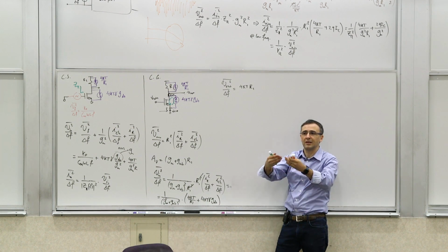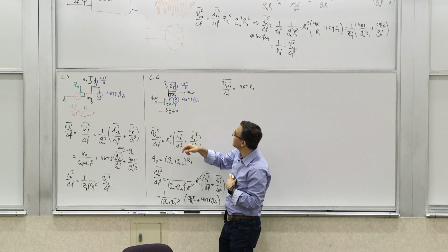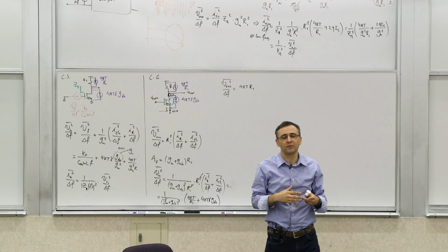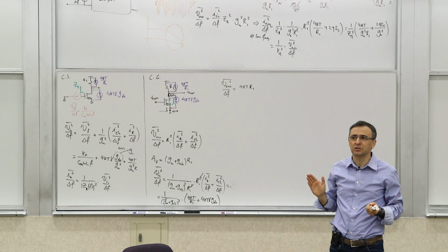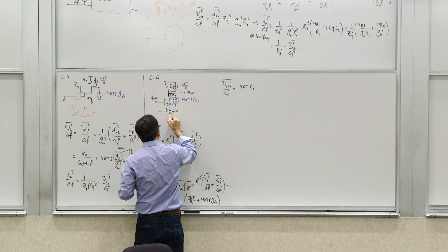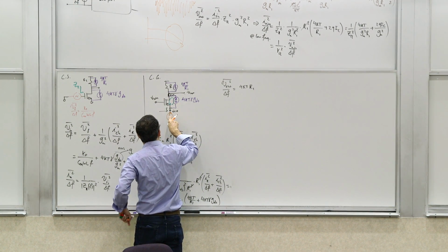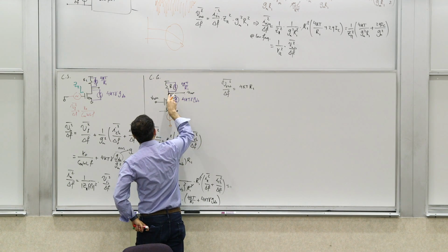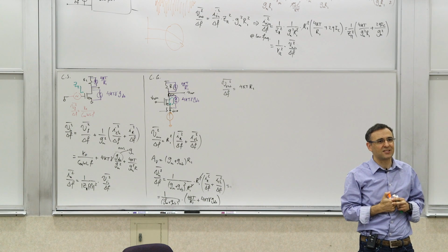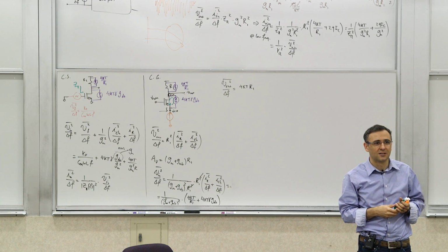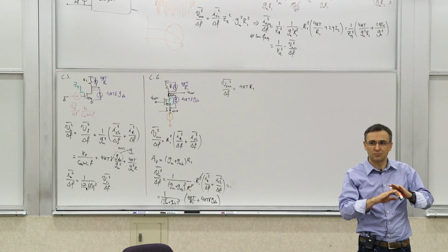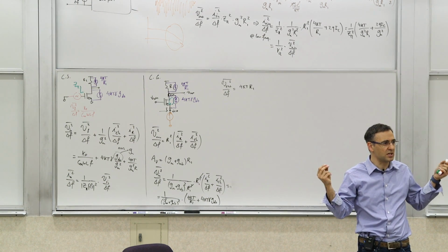And if you want to reflect it to the input, you have to look at the transfer function from that output voltage to the input current. What is it? Well, what is the transfer function from the input current to the output voltage for a current source now? If I put the current source back, what is the transfer function from this current to that output? What is the trans resistance, right? It's the ratio of output voltage to the input current. From a signal perspective, forget about noise, just from a signal perspective.